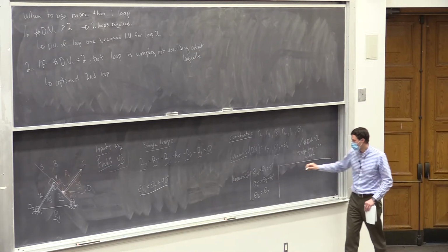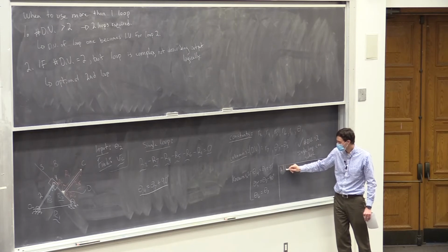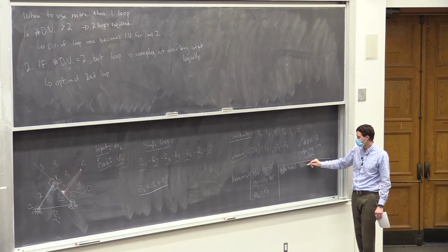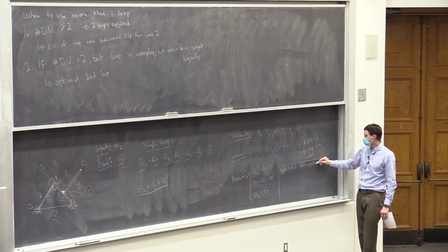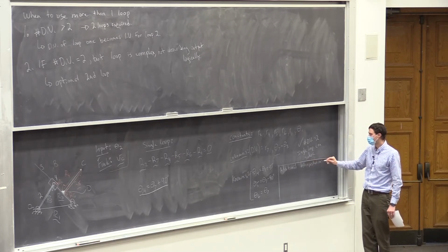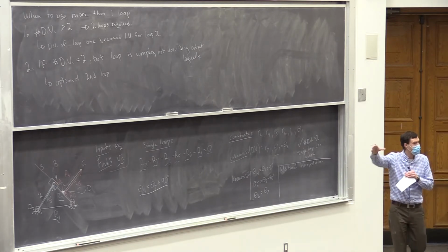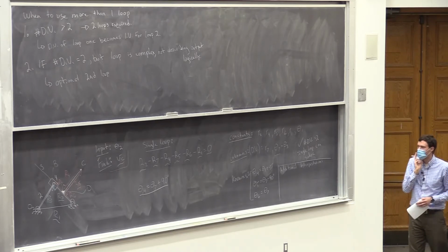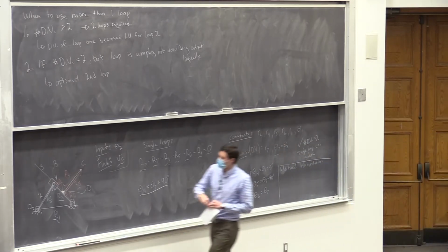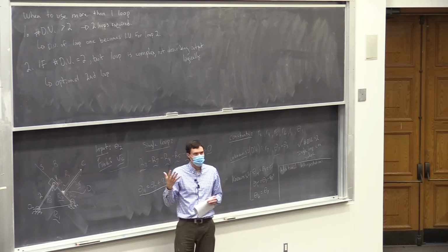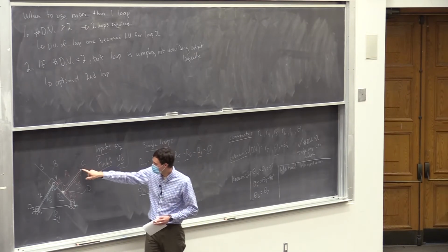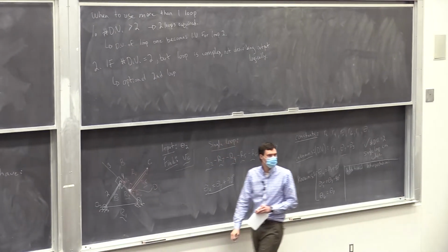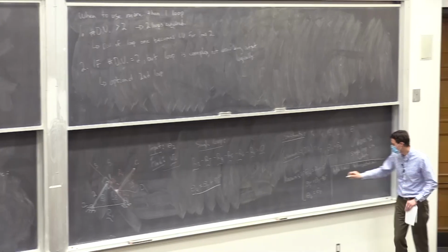So even though we can solve it, we need an additional equation. Or I called this last time the interpretation of the answer. Remember last time we were talking about the slider motion and positives and negatives and what those meant? Here we're going to have to do an additional equation to calculate velocity of C. And you could say, okay, this is almost like vector loop way of thinking. C, we could start at this ground point and do 6 plus 5. That's going to be the location of C.